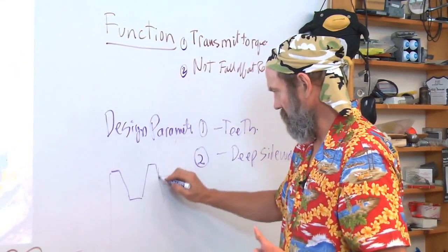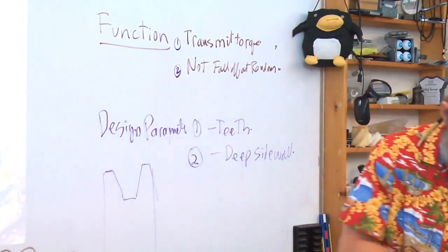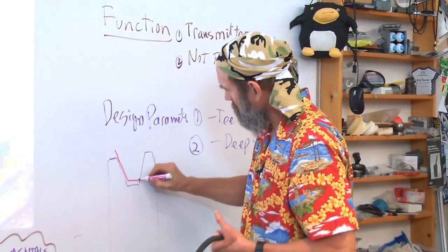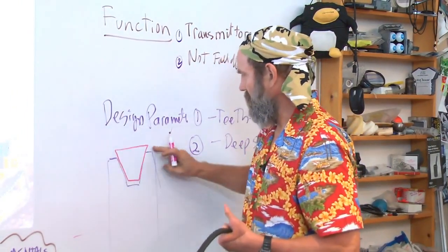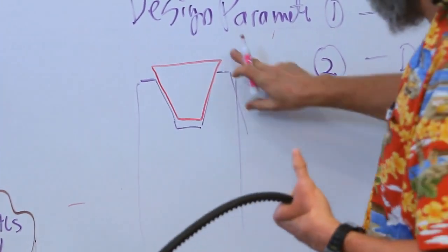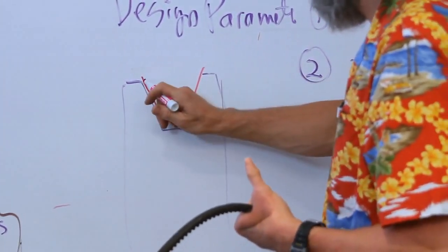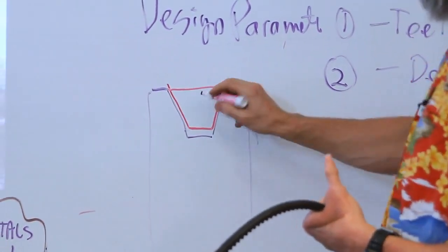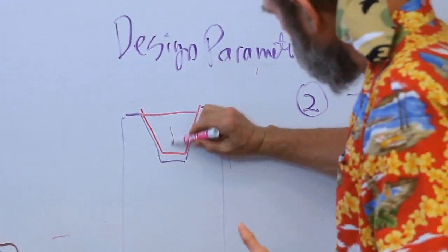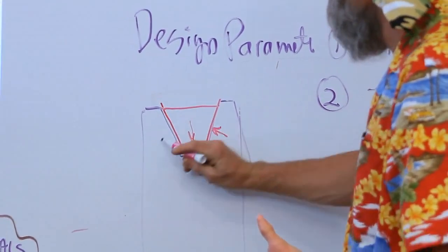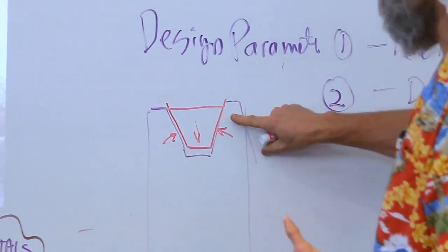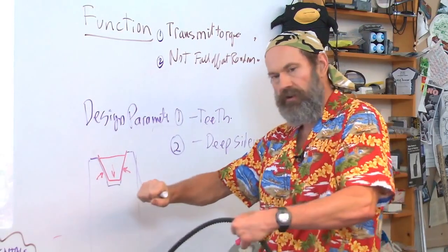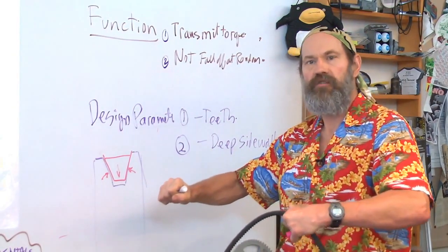Here's the sheave. And it doesn't actually stick out above. Shouldn't, in normal use. As the belt tension increases, it's jammed in here harder. The normal force increases, and normal force times coefficient of friction lets you pull harder. So it uses self-help to transmit more torque.